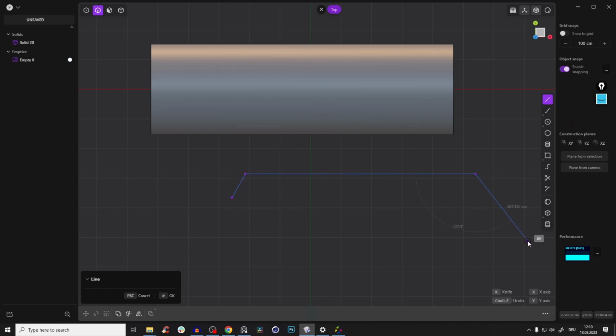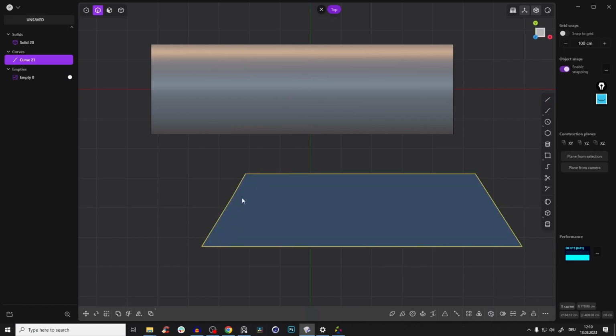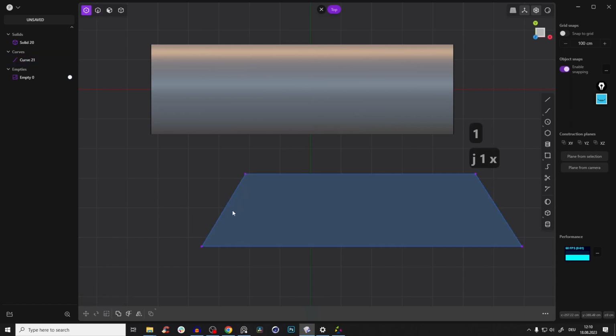So something like that, and just create here a big body, so it doesn't matter how it looks here, and join everything and delete this point here. So yeah, we just have this straight because we will create here a body and just Boolean that here inside. So I mean, we will subtract this body from the cylinder.